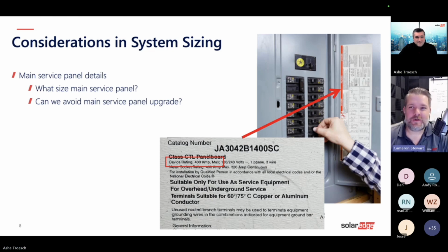Yeah, no, we do support multiple levels of power control systems for PCS. So we have export limitation, we have branch current management, where you're basically looking at our bus bar current management. So we're looking at the bus bar to make sure it doesn't overheat, so we can install larger systems on smaller service entrances. And then we also have charging from solar only. So yeah. Awesome. Thank you for the insight.